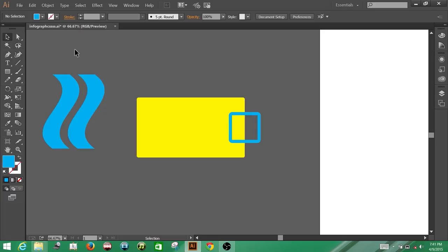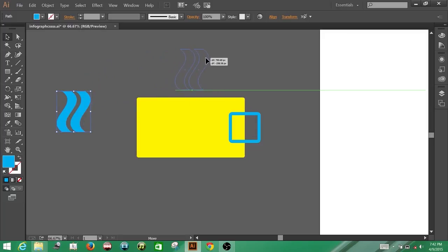With your selection tool, click, drag to select these objects, come up to this edge, click, hold down Shift and Alt key, and downsize them about this much. Release mouse, then keyboard. Pick up these objects and bring them up here. Make sure you line them up with the center of the yellow rounded rectangle beneath. Release mouse. Deselect.